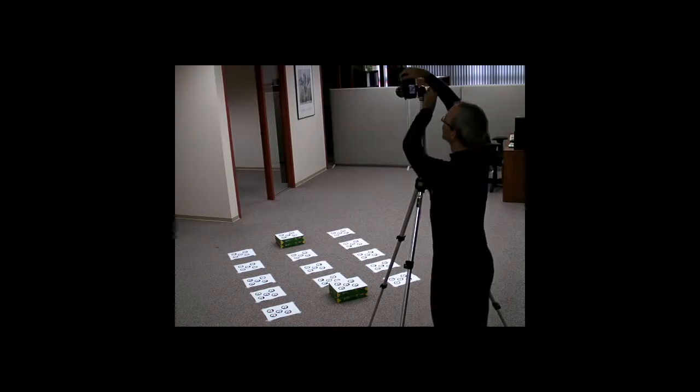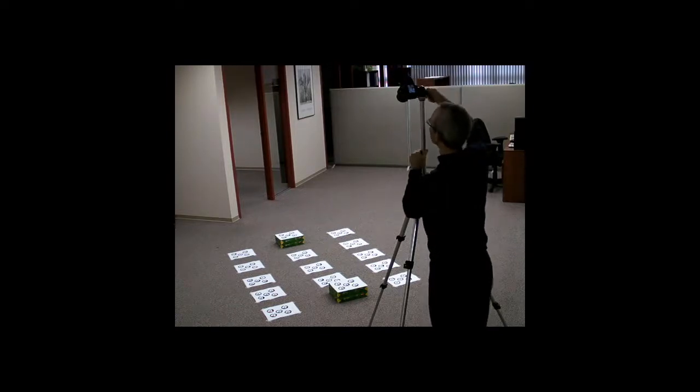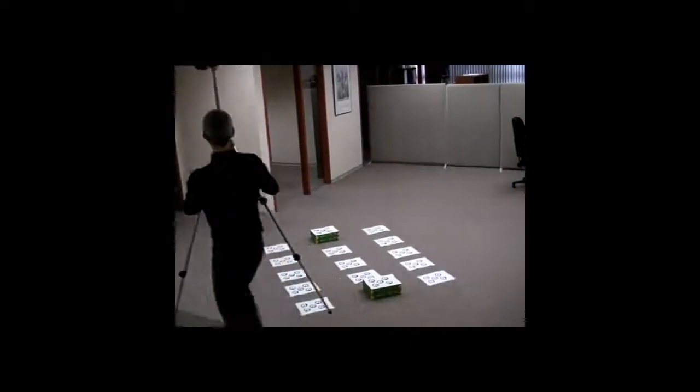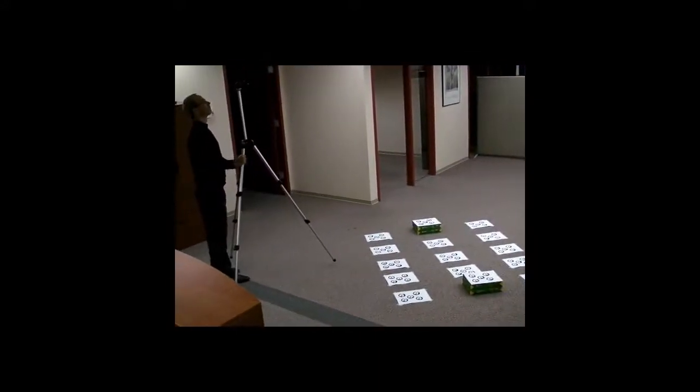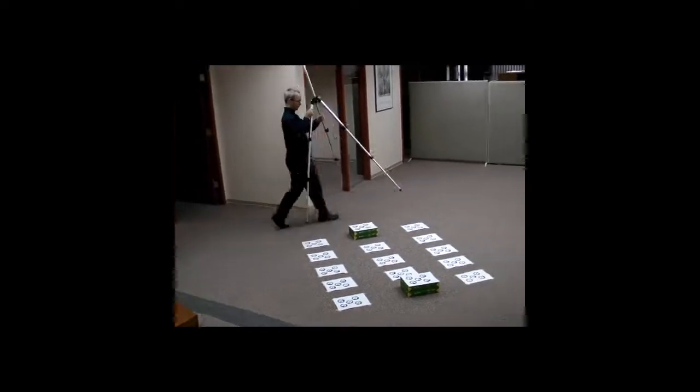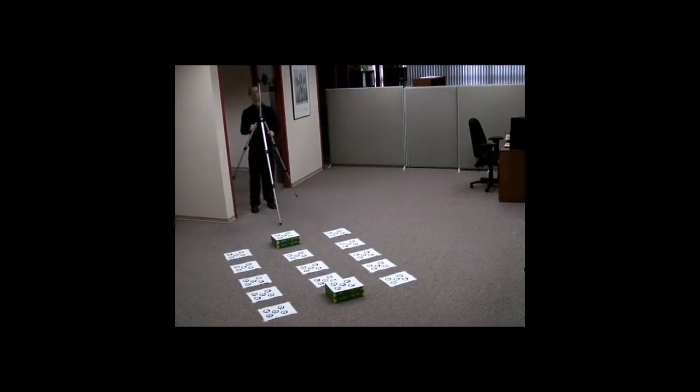This time, we rotate the camera 90 degrees to the left and take our last set of 4 photos. If your lighting is good and you have a fast exposure setting, you may be able to take handheld photos instead of using a tripod. However, any motion blur will decrease the accuracy of the marking, so when possible, we recommend using a tripod.